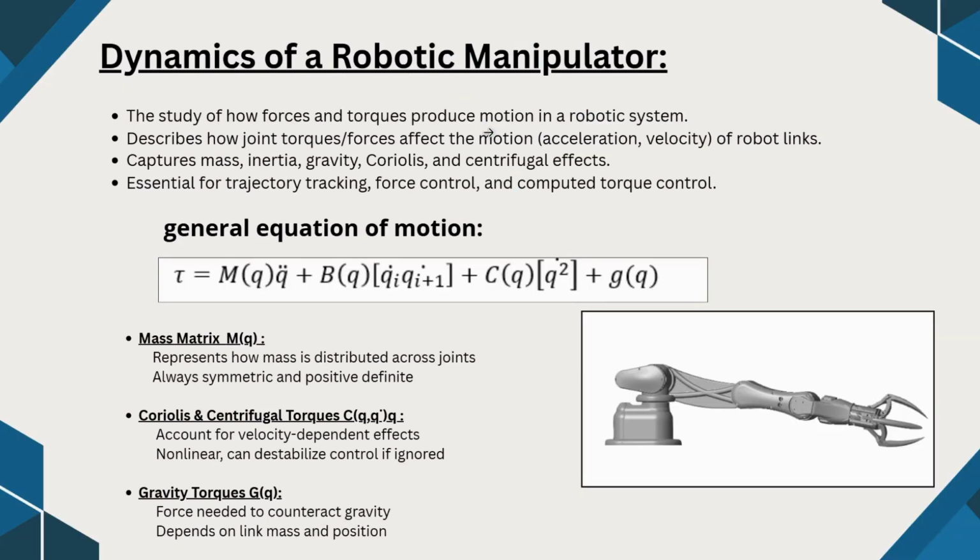The complete system is implemented in Simulink using a modular architecture. A reference trajectory is first generated, which is then passed to the computed torque controller. The controller computes the required joint torques, which are applied to the Simscape manipulator model. Joint positions and velocities are fed back to close the control loop.